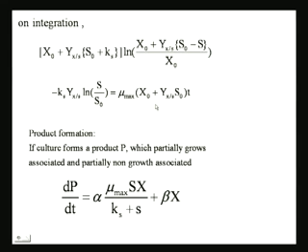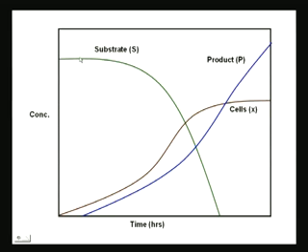So the cell is being produced, X, but because of the cell a product is being formed which has slope beta. And the substrate is here just like before, because the substrate is being consumed only in the cell formation. So exactly the same way as before. The negative of monod growth kinetics, as you can see, just the thing flipped around, because whatever is taken, the substrate is being taken up, consumed, and not formed. So it's exactly the monod growth kinetics flipped around. The cells, again, you see there's a monod growth kinetic, the formation of the cell, okay, but the product formation is not going to saturate out, as I said, because there is a term which is a constant, and it goes linearly increases.